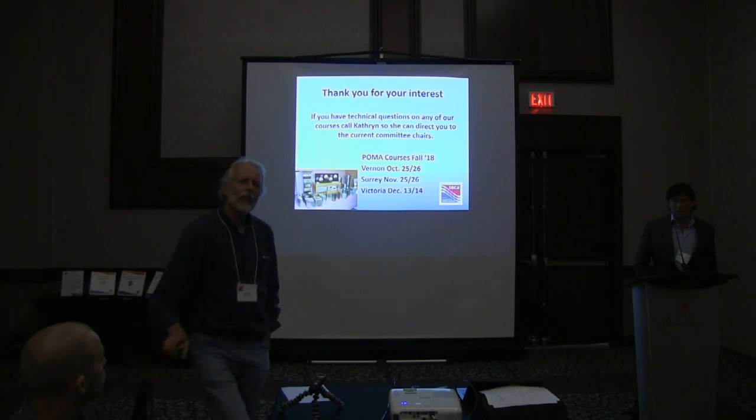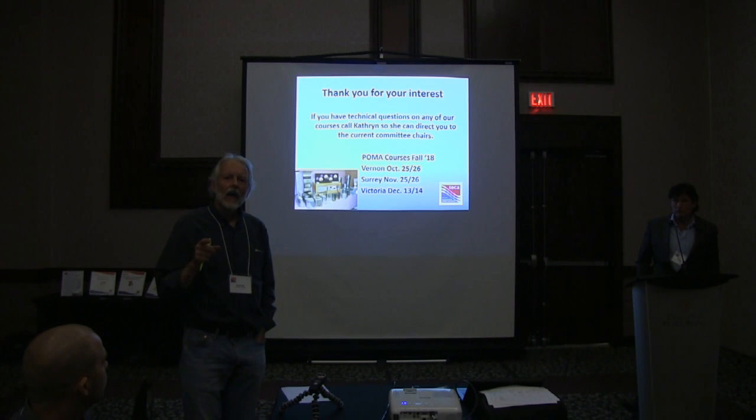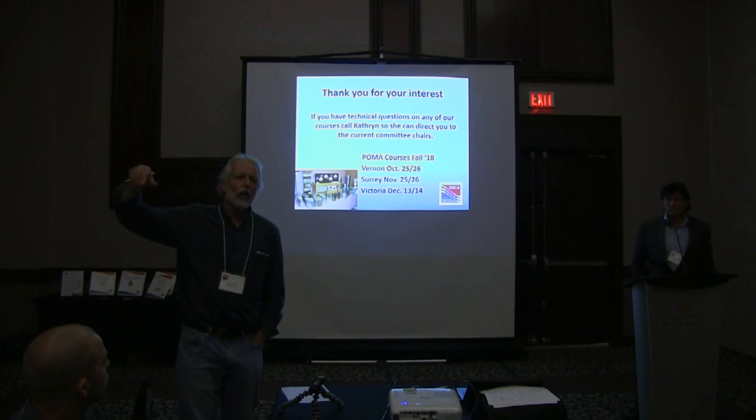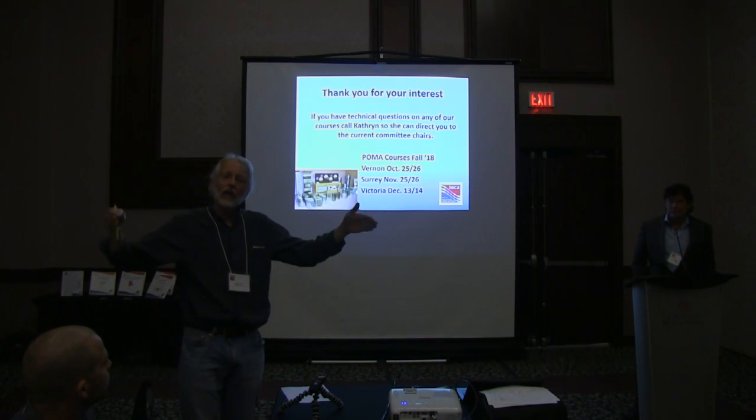Doug, you can't answer that because the electrical cost for heat or for cool depends on runtime. So there's no way you can answer that question unless you have a runtime or you have some other method of calculating how many hours of the year you're actually running at the heating or cooling speed.